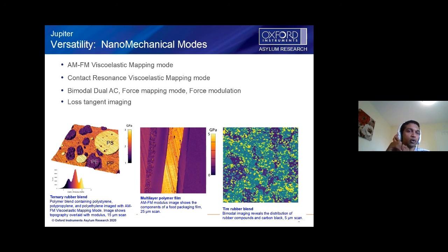Usually metal coated probes will work well. There are probes available that have a platinum coating on the tip side. Those will work well. The other thing to make sure is you set up the instrument in a way that you don't scratch that coating, because if you scratch that metal coating, then your KPFM data is going to change.